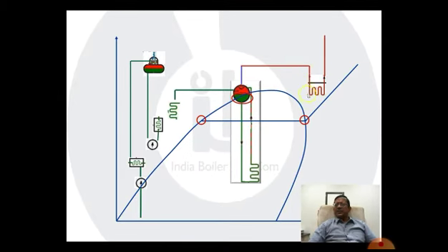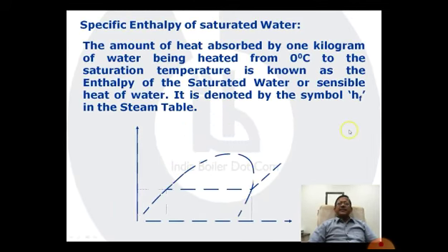But I would say that at the inlet of the superheater, the steam will be totally saturated, dry, and then the temperature will rise to the superheater temperature, right? So this is how we correlate with the boiler components, the heat gained at various boilers, heat exchangers with the temperature enthalpy diagram.